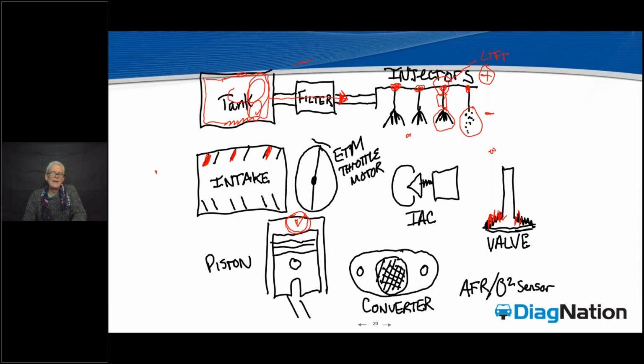Now, guess what, guys? The worse this gets on the high-mileage GDIs, this is where we get into MAF plausibility codes that are not calling a bad sensor or circuit problem. It's just saying this mass airflow data does not agree with this truth table.